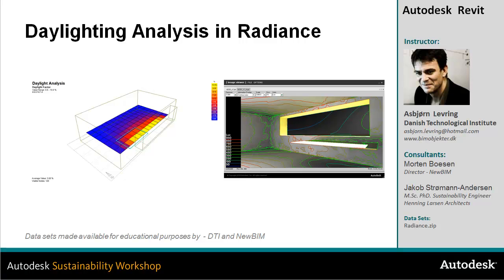In this video you'll learn how to use Radiance in connection with Ecotect for doing more detailed analysis of light levels within your building. Ecotect is really using an overcast sky and is only looking at geometry and a specific year, whereas we can use Radiance for looking at different sun streams we might need to examine to avoid glare and discomfort within the space.